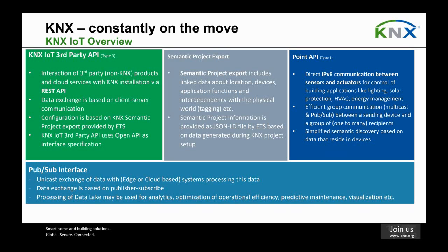So it answers questions like what devices are in this installation, where are they located, what functions do they realize, lighting, blinds, HVAC functions. And it also gives a hint, by means of tagging information, about what the actual device or the actual thing is that is connected to this KNX device.